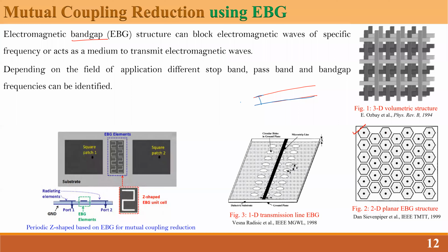So now if you select any one cell, for example this particular cell, what is it giving us in terms of L and C, inductor and capacitor? Say there is a current flow over here. Because of this path, you will be getting some kind of an inductor. And because of this separation between these two metals, you will be getting some kind of a capacitance, right? So you'll be getting something like that.